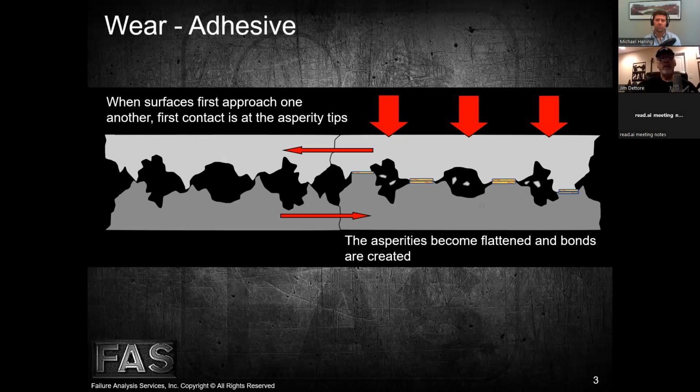Another possibility is that when we have the abrasive wear, if you recall last week, Michael, we talked about some of those particles plow through a surface, like a soft bearing surface. And as it plows through that surface, it raises edges or berms on either side of the cut or the groove that it's creating. When this happens, effectively those raised edges progress to adhesive wear very quickly because they reduce the clearance. Does that make sense? Oh yeah. Okay, so the abrasive wear can progress to the adhesive wear as well.